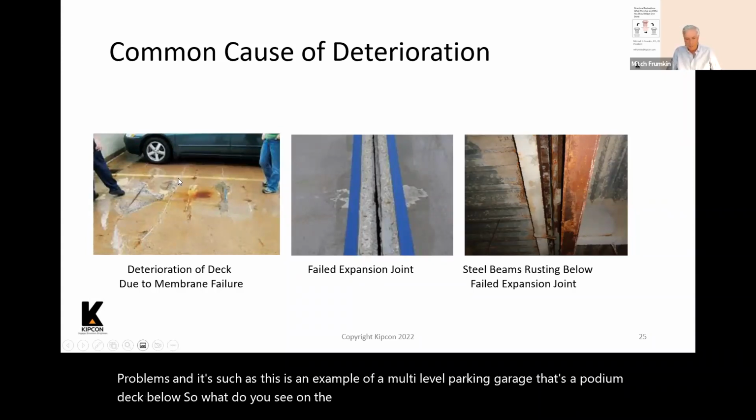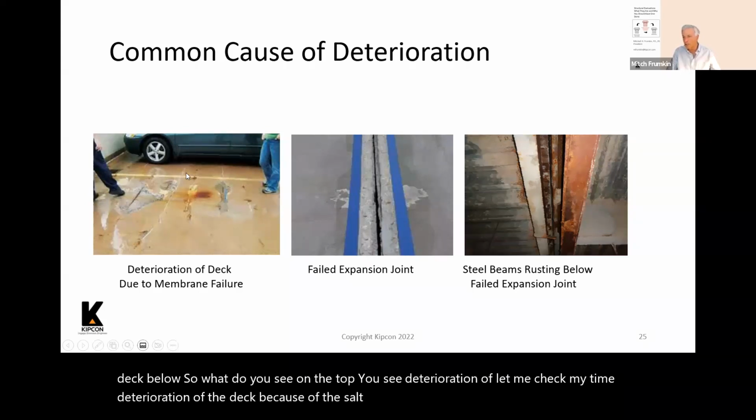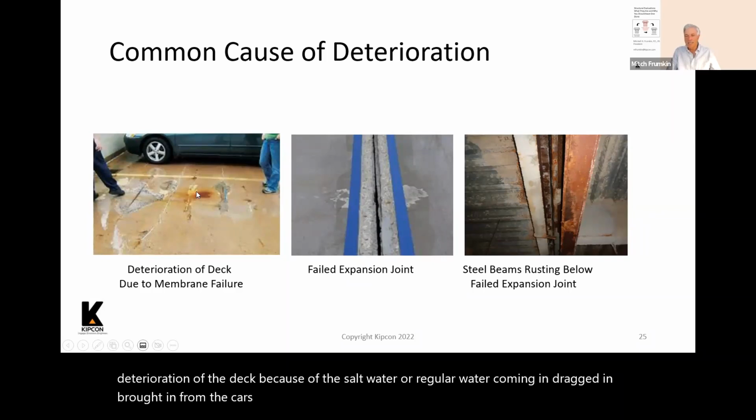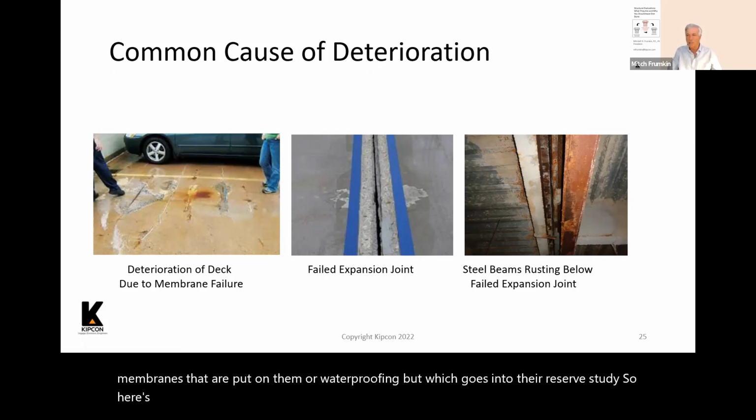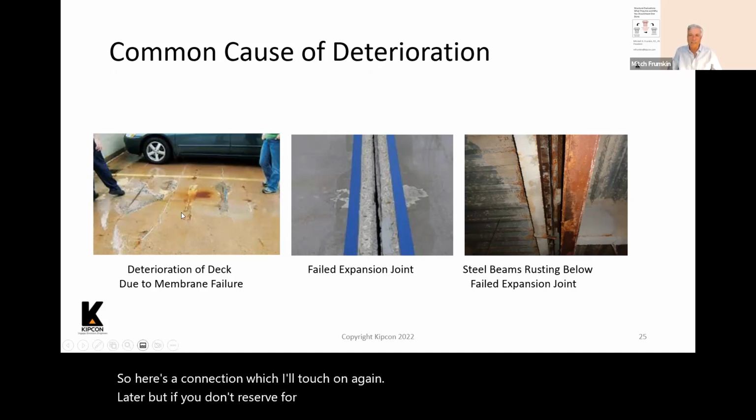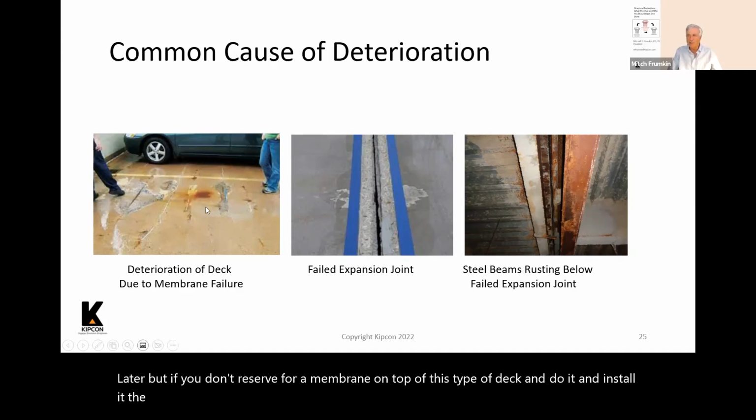You see deterioration of the deck because of the salt water or regular water coming in, dragged in, brought in from the cars, and it sits on this deck. In many instances, these decks have membranes or waterproofing put on them, which goes into the reserve study. So here's a connection, which I'll touch on again later. But if you don't reserve for a membrane on top of this type of deck and install it, the water is going to get into this concrete and start rusting the steel, like you see in